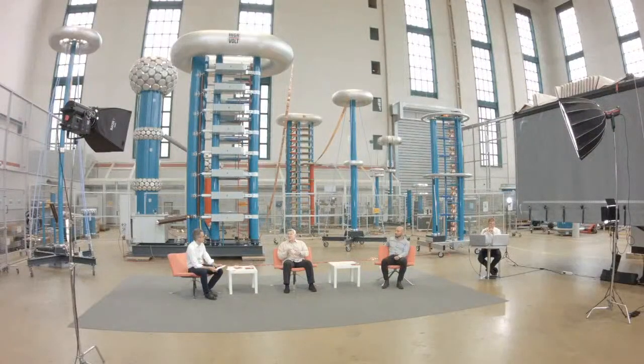Yes, one thing that we can observe more and more is that, especially for electromobility, the voltages applied during PD tests are going down, so the samples and objects are smaller, and we are testing not with 600 kV, but just with 600 volts. Because the voltage is not the important part, but the field strength. Especially in electromobility, where you have a lot of inverters and such with very sharp rise times, things that have never been tested for PD are now tested. Another example is traction transformers. Traction transformers for railway applications haven't been tested for PD for decades, and now it starts that even here this technology has to be applied.